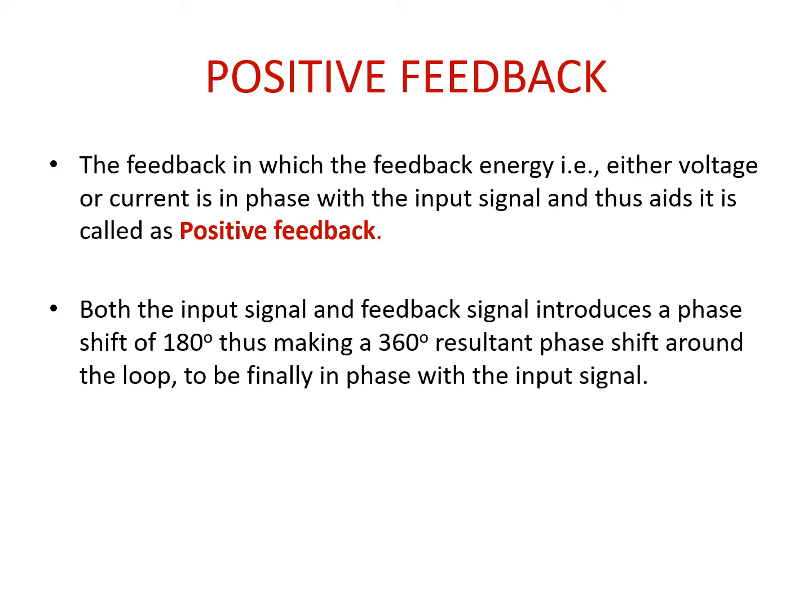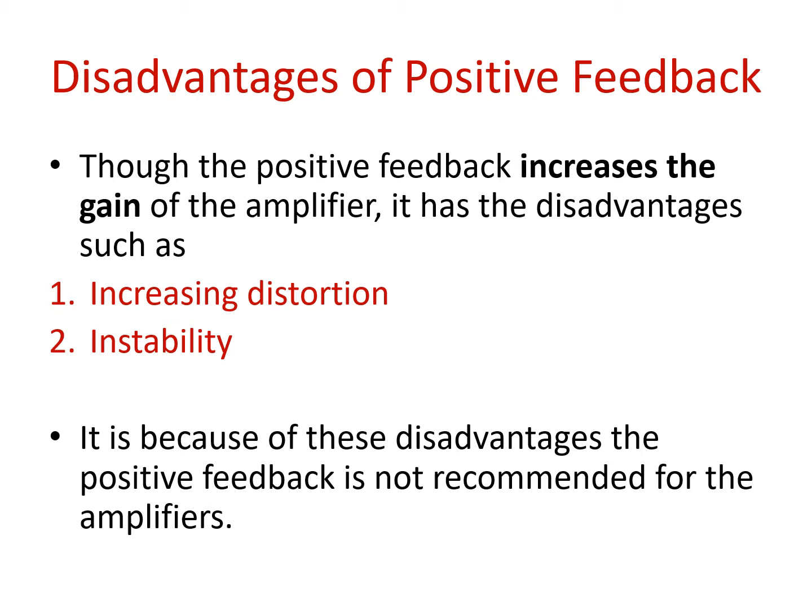So we need to see what are the disadvantages we face in positive feedback. Now what are the disadvantages that we see in positive feedback? Here we have mentioned two disadvantages. Okay, that is increasing distortion and instability. But again the advantage is also there, that it increases the gain of the amplifier, but it has disadvantages also, that is it increases distortion and instability in the signals.